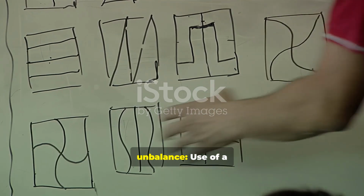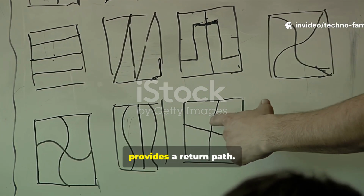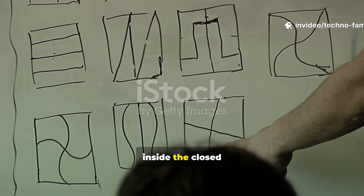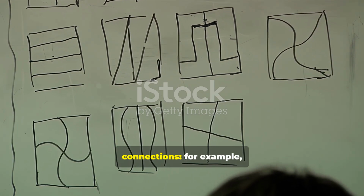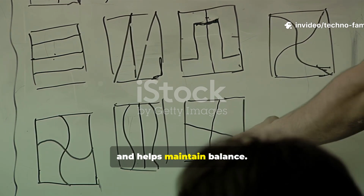Methods to handle unbalance. Use of a neutral conductor. In star connection, the neutral provides a return path. In delta connection, circulating currents inside the closed delta help balance the load. Special transformer connections. For example, delta-star provides a path for harmonics and helps maintain balance.